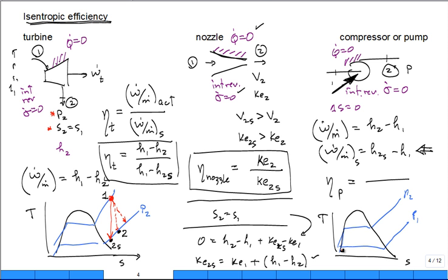Pumps like either saturated liquid or compressed liquid. Okay, so it's going to boost it up, straight up right there. Doesn't look that exciting, does it? Well, so you're going to have the minimum work, W dot over M dot, minimum divided by W dot over M dot actual. And that'll be the isentropic efficiency of our pump.